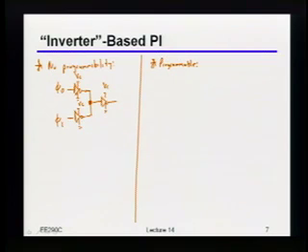Put on a power switch. Okay, you could do a power switch. More typically, that's done as some sort of a tri-state, or you can also actually do it with muxes. It's conceptually all the same. But let's just draw the tri-state version. So let's say I take that phi 0, and conceptually, again, I really just had one inverter. But now what I'm going to do is split that inverter into smaller pieces.